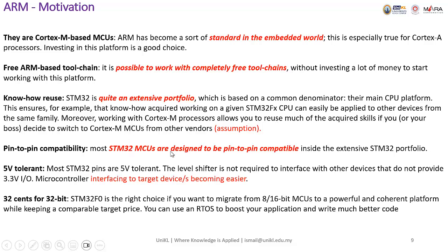Pin-to-pin compatibility: most STM32 MCUs are designed to be pin-to-pin compatible. 5-volt tolerance: most STM32 pins are 5-volt tolerant. Remember, the processor is working at 3.3 volts, so you cannot push it to 5 volts.